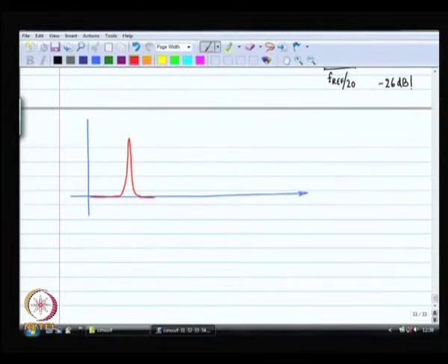This is the crystal oscillator spectrum, okay, and twice this frequency is my VCO spectrum. Kind of exaggerating the view, I have put a lot of bad phase noise over there, it is okay.